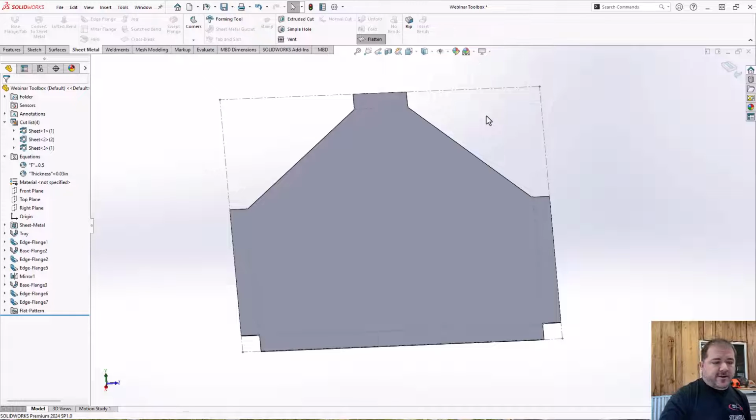So like we worked at a shop where everything was 16 gauge, so 1/16 of an inch, and all the bend radiuses were 1/8 of an inch. And so K factor worked out fantastically in that scenario. You also have situations where you're bending really thick material, or perhaps you're bending it really sharp. That's where the K factor starts to drop. You'll start to get into the 0.4, maybe 0.3 range on a really, really thick part. But here's the kicker. It depends on your machines. It depends on your materials. You can't really predict it very well.